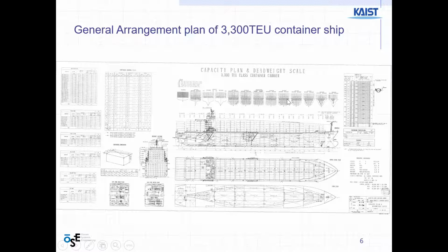And this top view, and also in the middle this section, is shown from the front of the ship. So three sectional views, three views coming from XYZ, right? Positioning toward the axis, you can draw different angles. And then the main topic of this general arrangement shows you what kind of room is there, which kind of room is used for which cargo, and which space allocation.